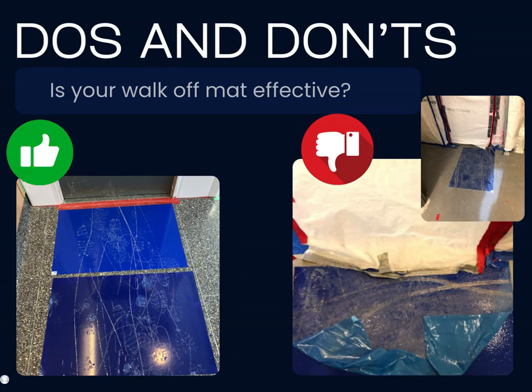Is your walk-off mat capturing dust and debris? We see some examples of ineffective walk-off mats in the images shown. If you are in a period of heavy demolition or workers are not following exit procedures, mats will quickly lose tackiness. Ensure you are changing them often to prevent dust from escaping from the job site.